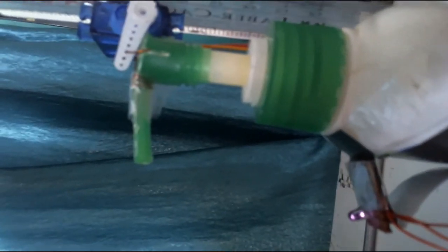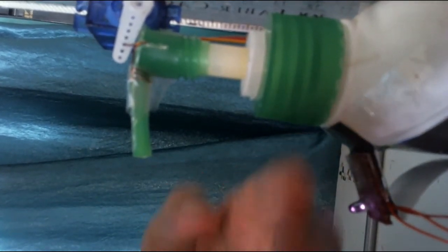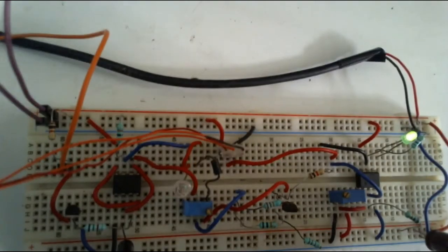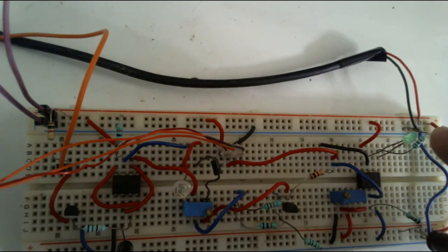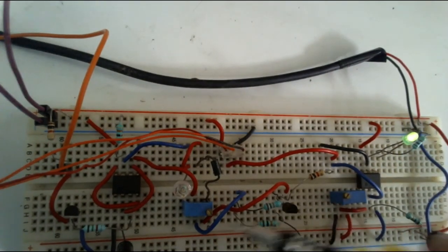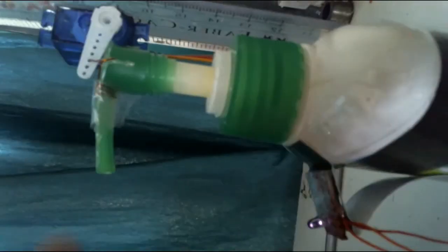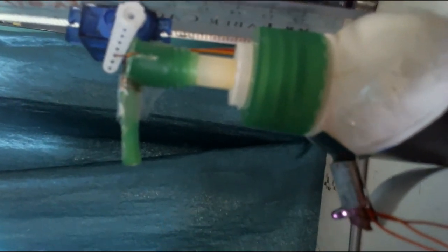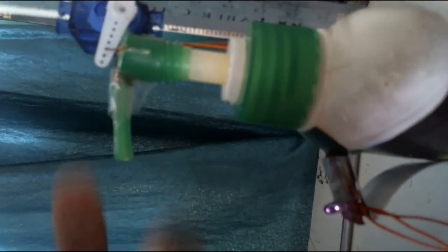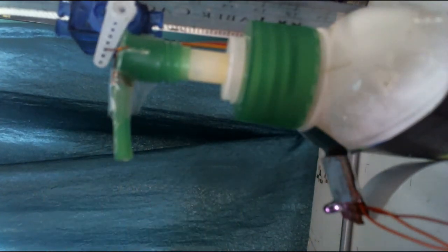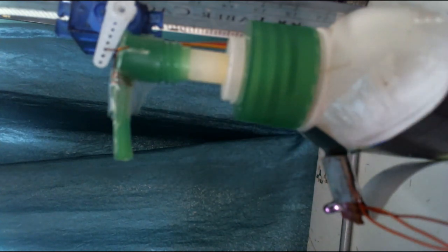So this was the circuit, and if you're more interested in this soap dispenser, how it works is, when I place my hand beneath this, it interrupts the sensor, and that sensor turns off the output of this comparator, which brings these two resistors in parallel with this potentiometer, which pushes the servo angle down. I'm just working on it right now. So this was the video.